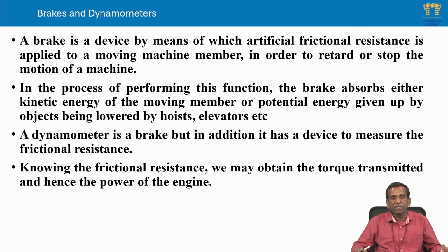But a dynamometer is basically a brake which, in addition, has a device to measure the frictional resistance, that is, how much frictional resistance is needed to stop, slow down or retard the motion. That we can measure using a dynamometer. The additional function of a dynamometer is knowing the frictional resistance so that we can obtain the torque transmitted and the power of the engine from this.